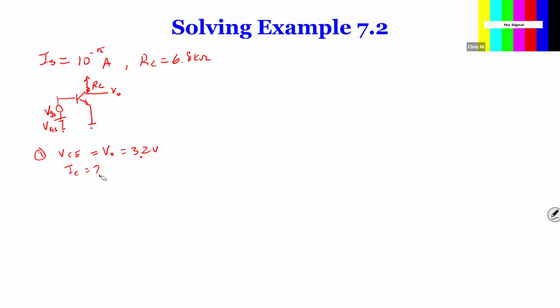So what we're saying is, okay, we have to know VCC, which is given at 10 volts. So those three numbers are given, RC given. So they want VCE to be 3.2 volts. So from here, we want to determine what IC is. Is that simple? How?